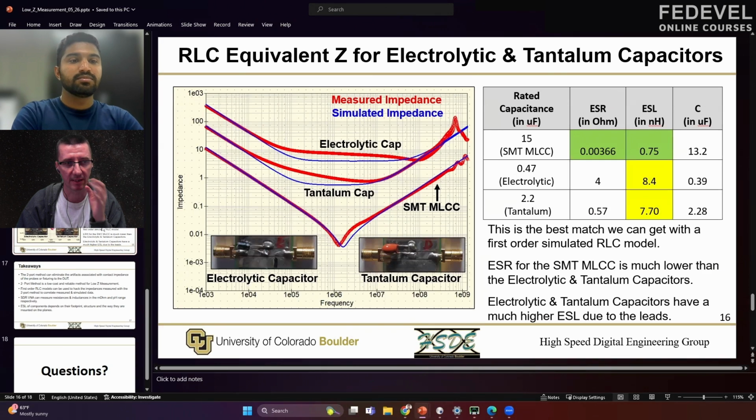So basically, they could play with these standard components. They could maybe measure the components they use and then create perfect models for the simulations. Or in the next step, they could maybe measure the impedance on their own boards. What would you recommend? So the next step I would recommend is to move to measuring something like the impedance profile for the PDN of maybe a microcontroller.